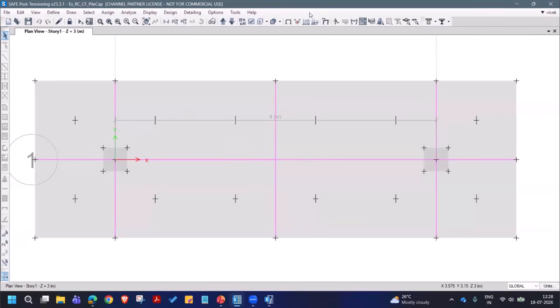So the crack width that is implemented is based on Eurocode. I think the K1, K2, K3 parameters are the only things that are available to you to modify, and you can get this crack width check. It is very similar to Indian code, so you can use the same feature. So only one code base is available for this.